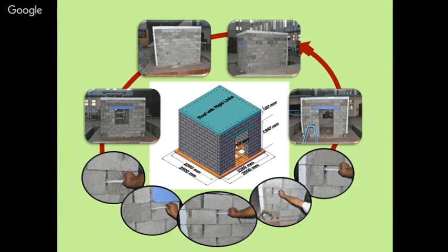Is plastering very difficult in this system? No, plastering is just similar to what you do for your normal structure. After joining the bricks with one another, you prepare the plaster in a 1:4 mix and apply it. That is how this is a normal building. Blocks shake during an earthquake, but your normal brick structure also shakes during an earthquake. In that case also your plaster will crack.